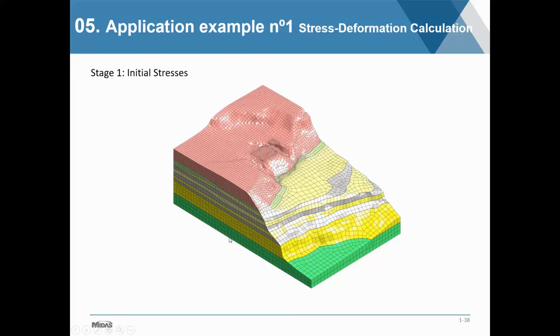So this example is actually a construction stage analysis. The first stage will be just initializing the stresses. You can see, even by the shapes of the meshes, that this is going to be an area that will be overlapping for a little bit, in the sense that elements will be removed and then reactivated later as a different material. That's another key difference, as we'll see, that is going to affect our export process for this particular example. Midas can handle having multiple meshes